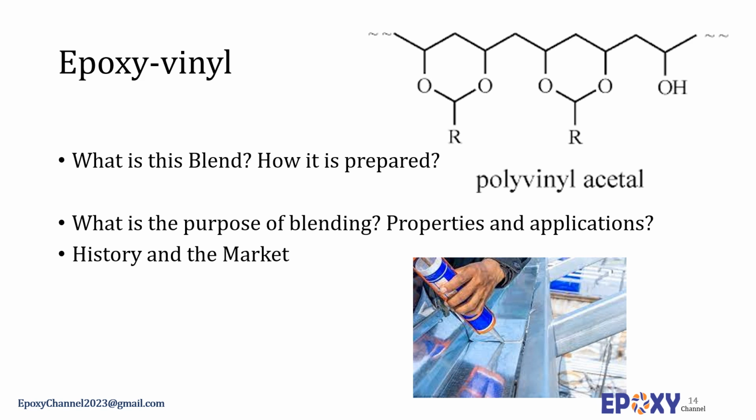A composition consisting of a plasticized polyvinyl chloride copolymer and an epoxy resin can be cured with an aliphatic polyamine, which will cross-link by reacting with both resins. Polyvinyl butyral is used in combination with thermosetting resins to form tough, strong structural adhesives. The most important adhesives for gluing of metals are bisphenol epoxy resins and phenolic resins modified by the addition of polyvinyl acetals, for example, polyvinyl butyral and polyvinyl formal.